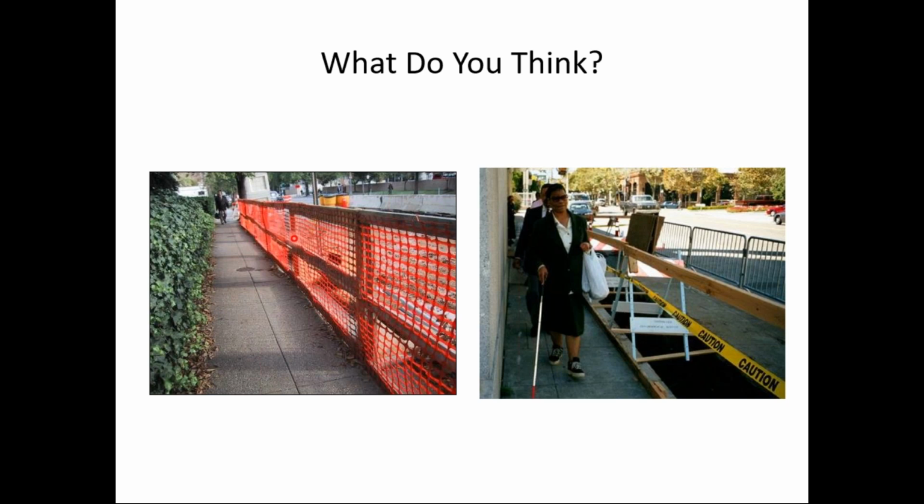That, in this arrangement, I think is acceptable. If we just had the netting hanging down from an upper rail to the bottom and there was no toe board or kick plate or edge down here, that would not be acceptable because that would not be a detectable edge. But having said that, the one thing I would caution is if you're going to use an arrangement like this, make sure that periodically you check the tautness or tension of that netting.